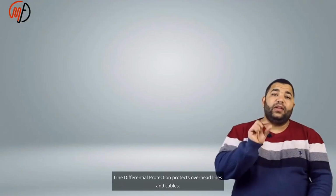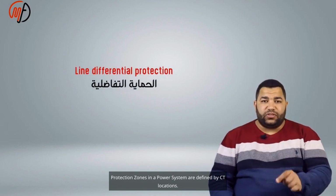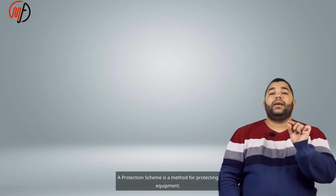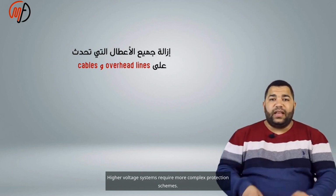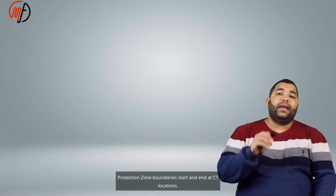Line differential protection protects overhead lines and cables. Protection zones in a power system are defined by CT locations. A protection scheme is a method for protecting equipment. Line protection includes various protections. Higher voltage systems require more complex protection schemes. Protection zone boundaries start and end at CT locations.